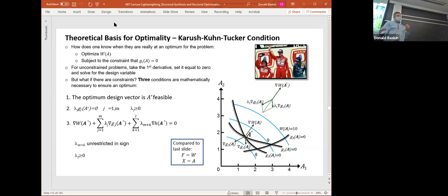The way that we structured that requirement into a constraint was that the stress the actual part has on it minus the critical stress equals 0. Then you can easily plug in for sigma, stress and critical stress, based on the geometry of the beam or the bar or whatever it was. You guys remember that? And then you can set that equal to 0. So that's why this does make sense.